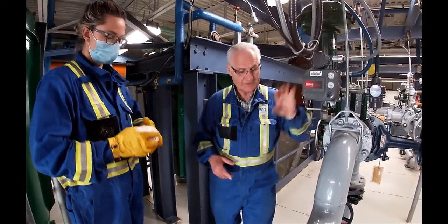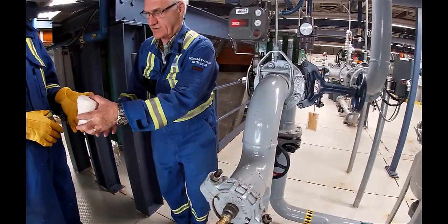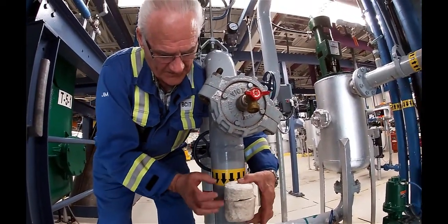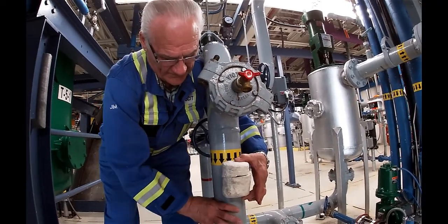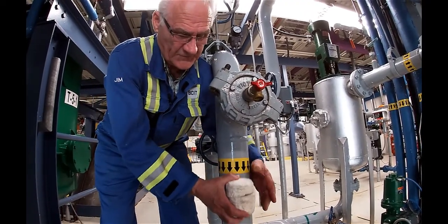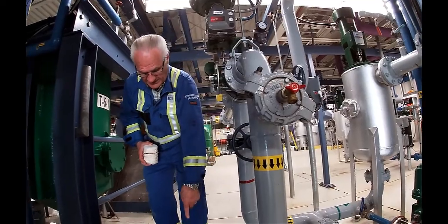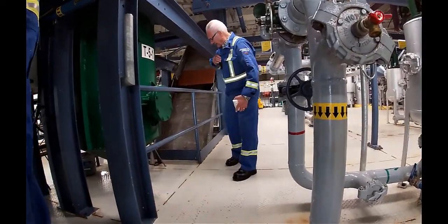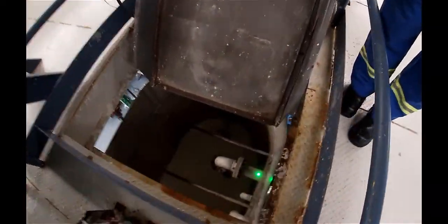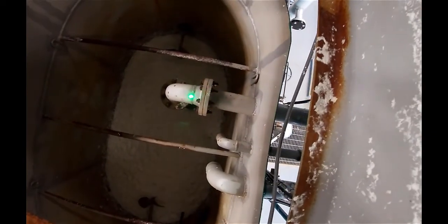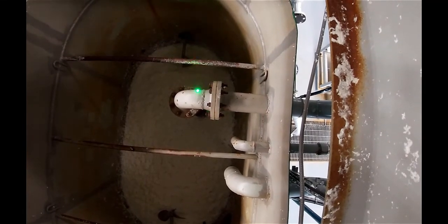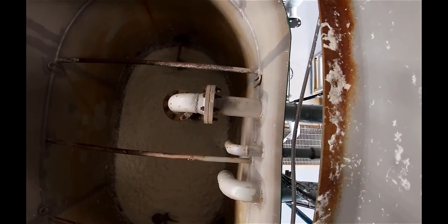You can hammer them together and see how hard they are. That was stock that was sitting in the bottom part of this line here. If you take a look at the size of this piece of fiber, that pipe was absolutely plugged full and we couldn't get it out. It was actually further down the line. If we go right down across the floor here, and Ray, if you follow me, that line there is where that stock comes out, and it goes down this pipe and ends up going down into the stock tank at the bottom. That length of pipe at the end was where this was jammed.